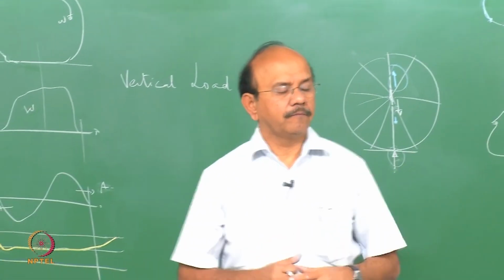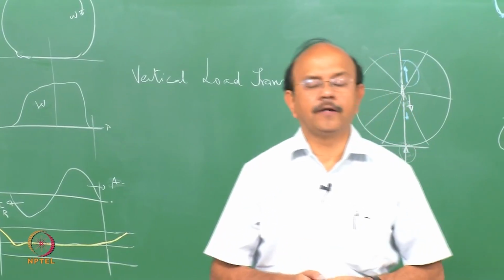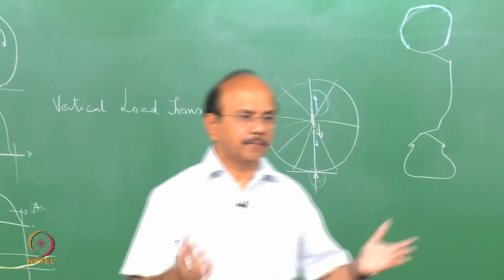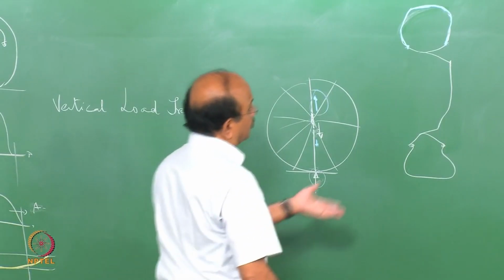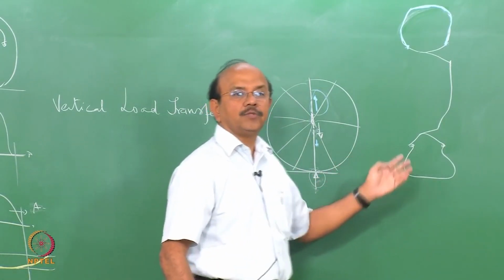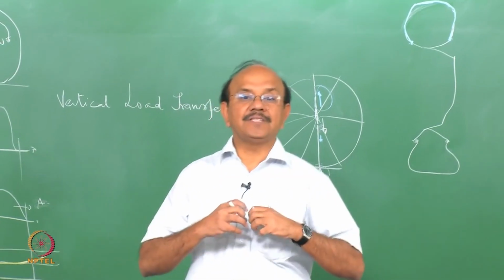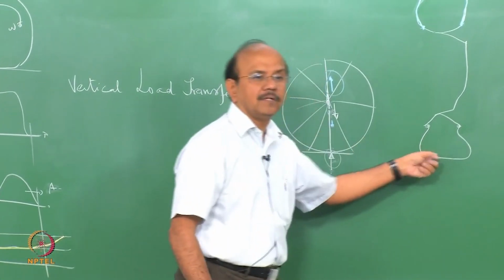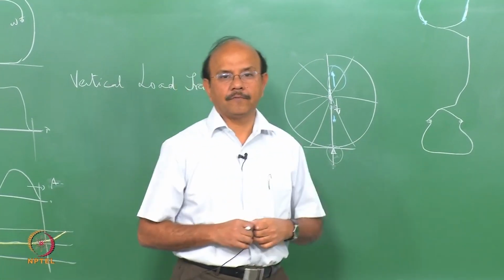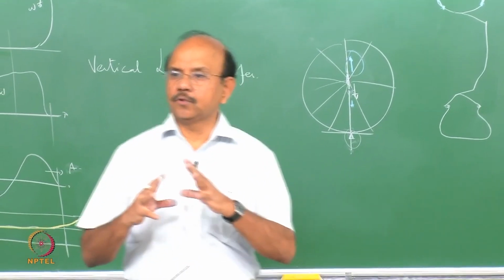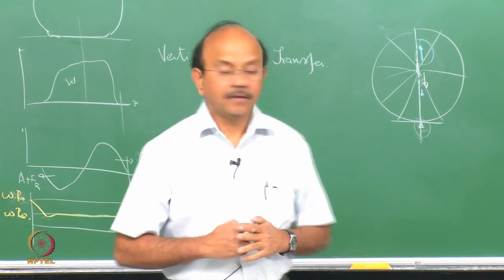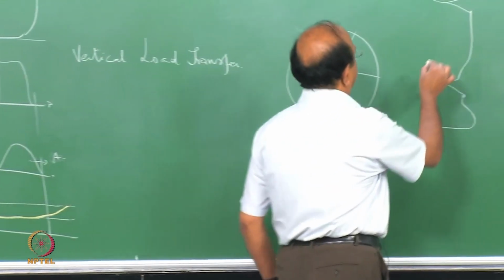You go to a shop and you fill it up, 32 psi is the pressure you keep. So that pressure is what gives the equivalent tension in a spoke to the sidewall. Is it clear? That gives the tension.